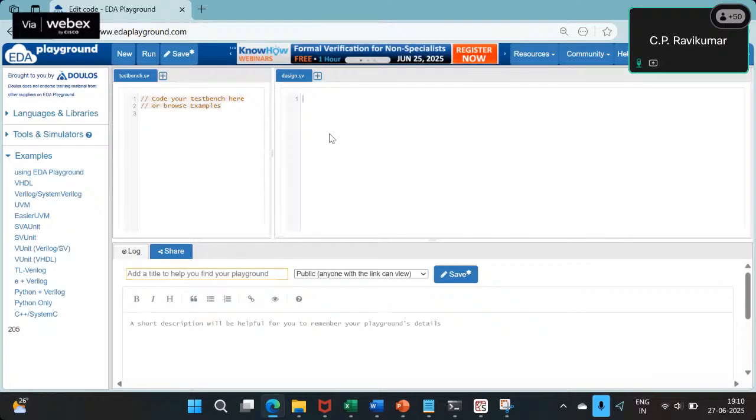Why are you saying we should use a binary adder? We are trying to add BCD numbers, right? Yeah, but a BCD adder is usually implemented by using binary adders, 4-bit binary adders for each digit.